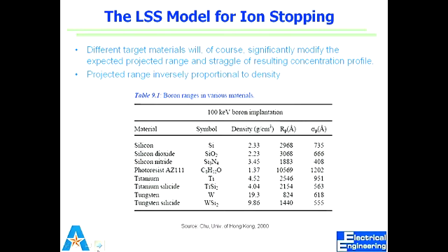Then this plot will tell me how thick silicon dioxide should be to be used as a reliable mask. It can be used as a mask even if you use 20 nanometer, but a reliable mask is one where no ion passes through, or negligible ions pass. Does that make sense, guys? So you can expect something like this. I would expect you to know how to figure these simple things out. Figure out upper limits and lower limits on these guys, right? So here we are talking about the lower limit.